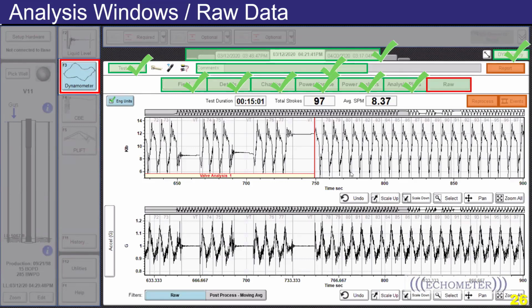On this screen, you will have either a section, or you can expand the white area here to observe the whole trace or dynamometer session. On the top, you will always have the load calculated or measured, either with a PRT or a load cell. The bottom chart will change a lot based on what kind of sensors you acquire.